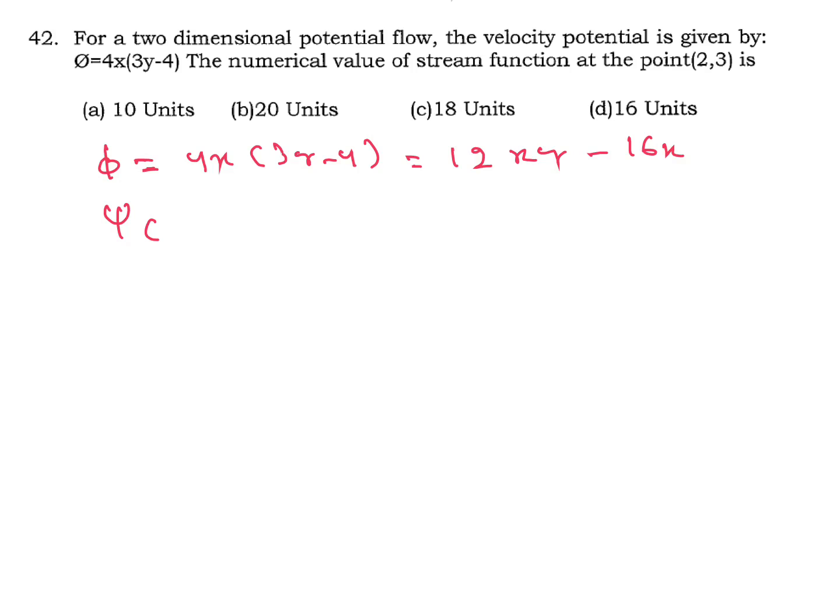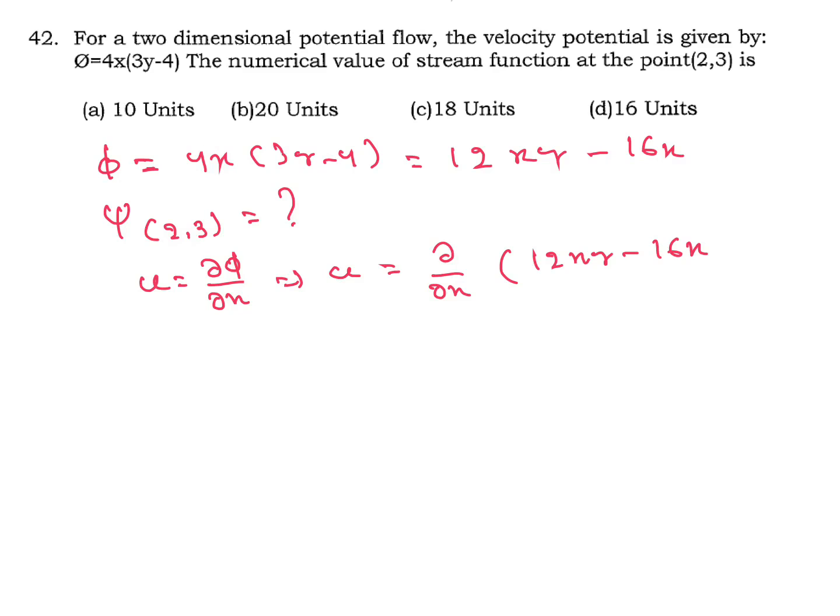So we know u equal to del phi by del x. So u equal to del by del x of 12xy minus 16x. So we will get 12y minus 16. We know u equal to minus del psi by del y, stream function.